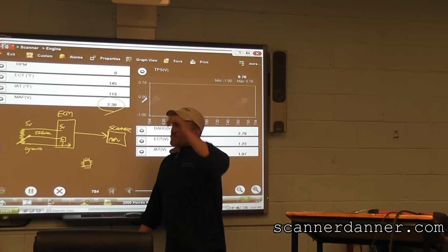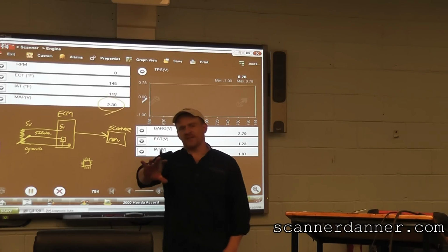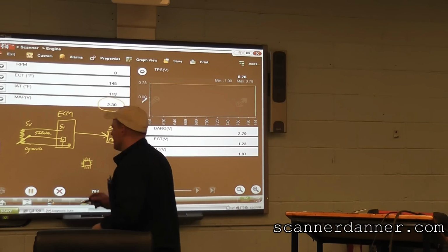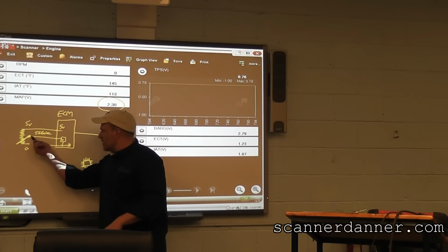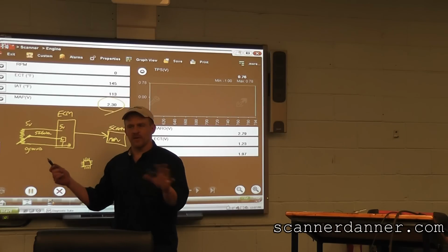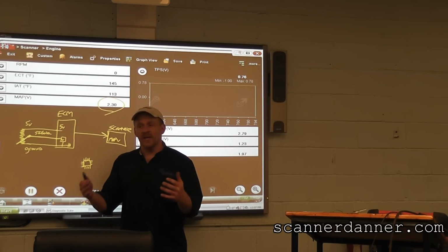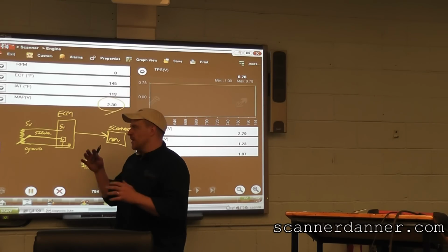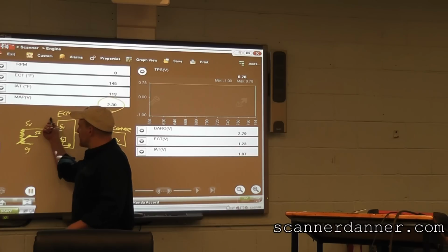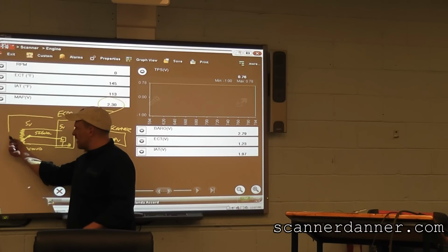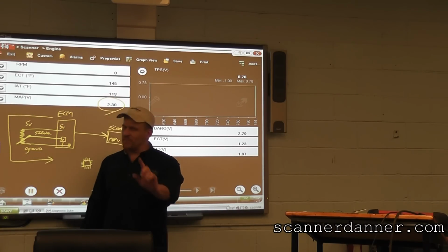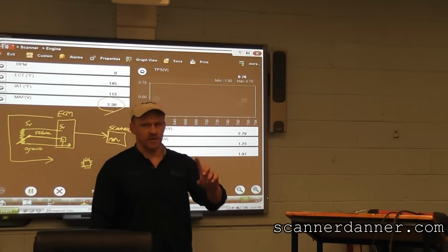Anyway, here's the perspective you guys need to have on this potentiometer circuit. This signal wire does not in any way, shape, or form carry current flow. Okay, there is current flow, even though it's in the microamps, because we need to have a voltage drop on this circuit. So we have a steady 5 traveling this way across a fixed resistor on its way to ground. This is not exactly how the MAP sensor works, but this is how we're going to think about it.